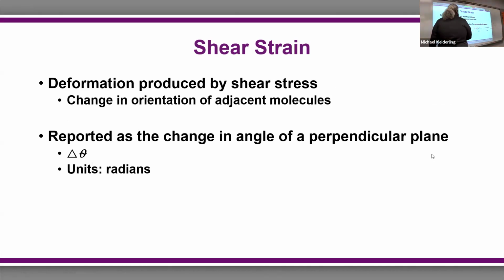Now, shear strain is reported as a change in the angle of a perpendicular plane. Shear strain is delta theta. It's reported in units of radians. So it's about the angle change in radians.